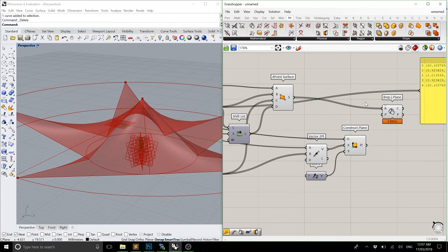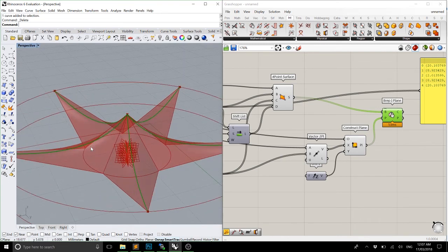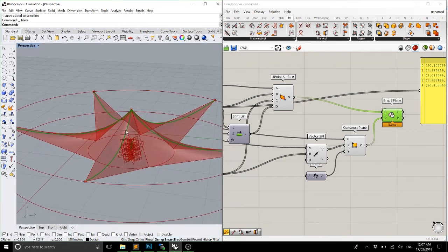It's like sort of saying that something is a curve. So lines, circles, arcs, ellipses, splines, they're all curves. So surfaces are boundary representations. So we're going to find the intersection of that with the plane. And that's going to generate a curve that slices all the way through. And this curve is effectively the element that we're going to find a point on to generate the triangles.